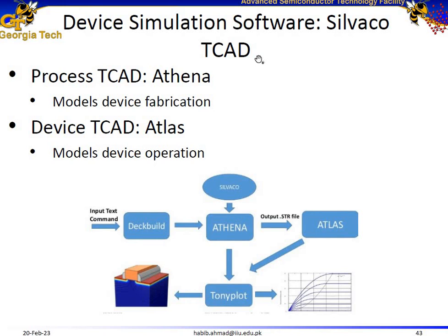TCAD. Silvaco TCAD basically has the main modules Athena and Atlas. Athena actually simulates the process TCAD for you, like how you grow different layers of a device. So Athena simulates that, but we will not deal with Athena. We will deal with Atlas, which simulates device TCAD for you.